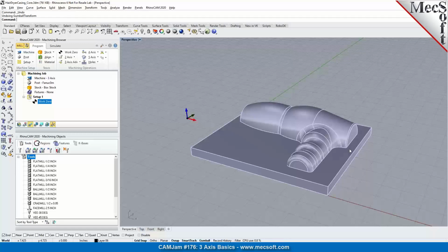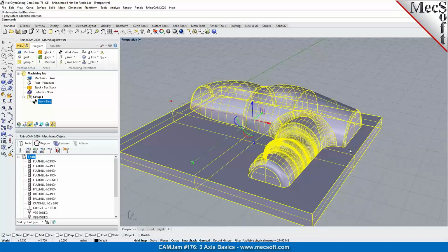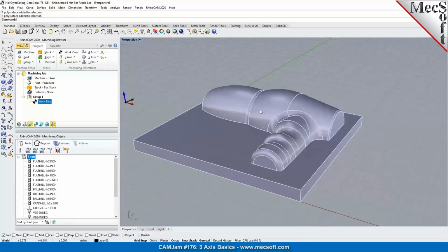We could work with solid geometries, which could be made up of a bunch of surfaces stitched together, a poly surface. In this particular example, you're seeing a poly surface where multiple surfaces are joined together, which forms a closed poly surface, or it could even be an open poly surface. You could program 3-axis toolpaths for geometries that are both closed or open poly surface.